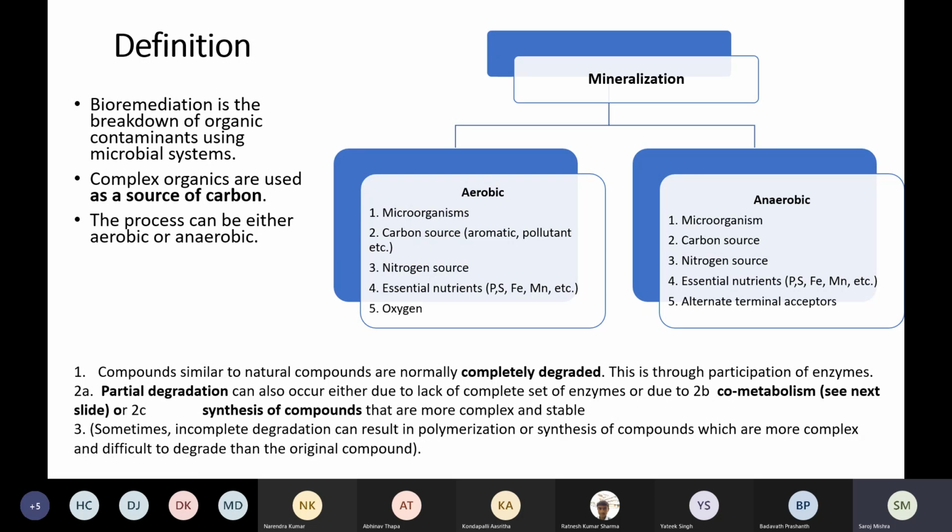For example, when you take this groundwater, when you take this contamination of the soil by leakage of underground petroleum tanks, okay, there the oxygen is not there. So are we trying to say that we will not be able to conduct a microbial remediation process simply because oxygen is not available there? And why are you looking for oxygen? Because you are looking for oxidation. Or rather than oxidation, you can use the term breakdown.